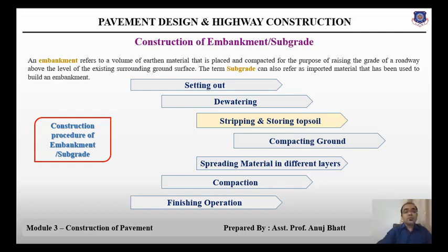The topsoil should not be unnecessarily subjected to traffic either before stripping or when in a stockpile. Stockpile shall not be surcharged or otherwise loaded, and multiple handling shall be kept to a minimum.